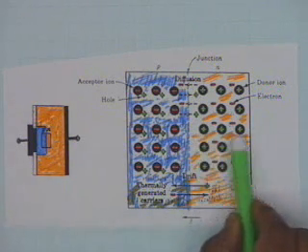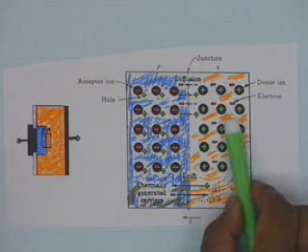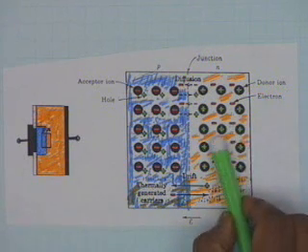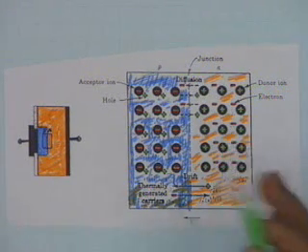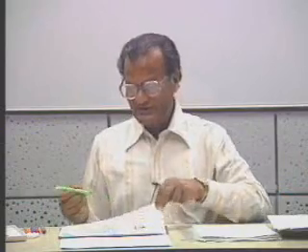But if you go far away from the junction, for example here, if you measure over a non-zero area, it would be zero charge, because there are fixed charges as well as mobile carriers. There are electrons as well as holes, and the total silicon bulk is electrically neutral, and therefore this region is also called space charge region. That means in the space that is available, you shall be able to measure charge only in this region.